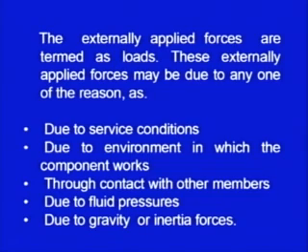The third is through contact with other members. This is the basic thing in machinery. All machine components are connected with each other, and whatever force, torque, or speed is transmitted, it is transmitted through this connectivity. So all components within the machine, or external objects, if they are associated through contact, always bear different forces through the different contact members. The fourth one is due to fluid pressure. Either buoyancy forces or hydrodynamic forces are there. These forces are due to fluid pressures, because the fluid always has some strength through which it provides impact or steady state forces. So these are also in the category of externally applied forces.